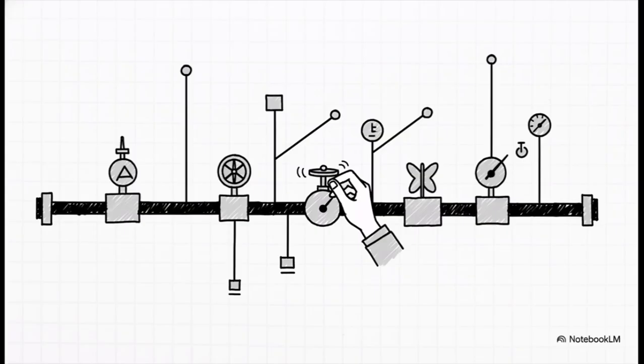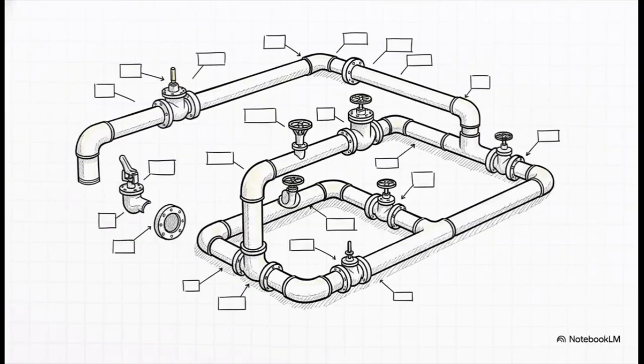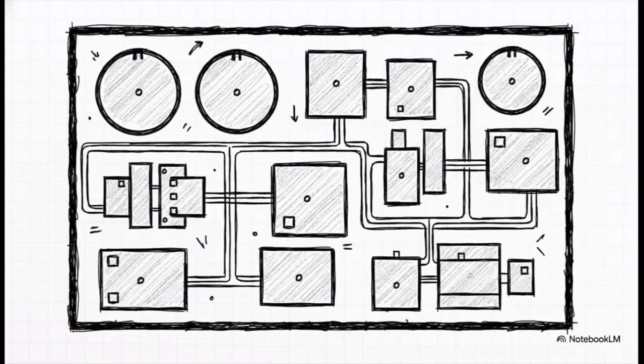this process. To understand how it fits together in the real world, there are also piping isometrics, which give a 3D picture for construction and show how the pipes are routed across the plant. Finally, we have the plot plan and the general arrangement, which act as the master map for the construction and the location of each piece of equipment, and are used mainly in the construction phase.